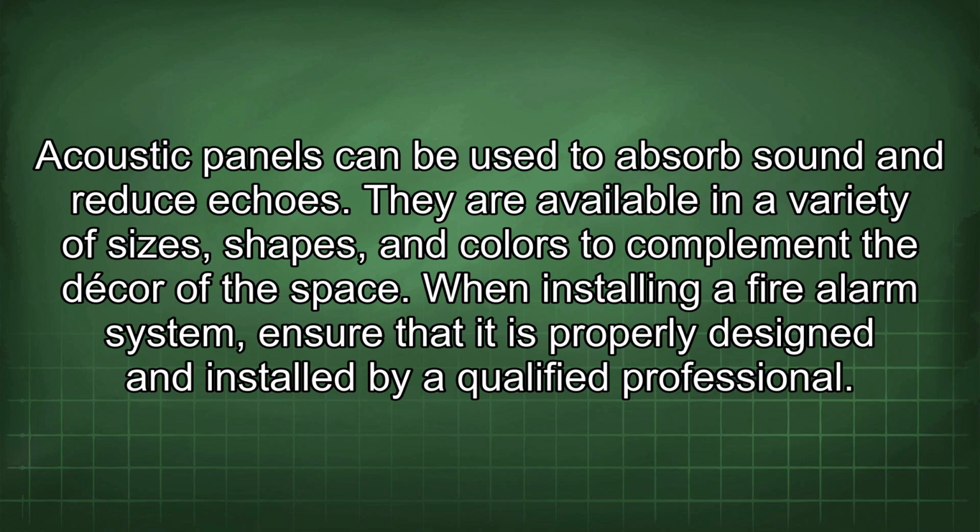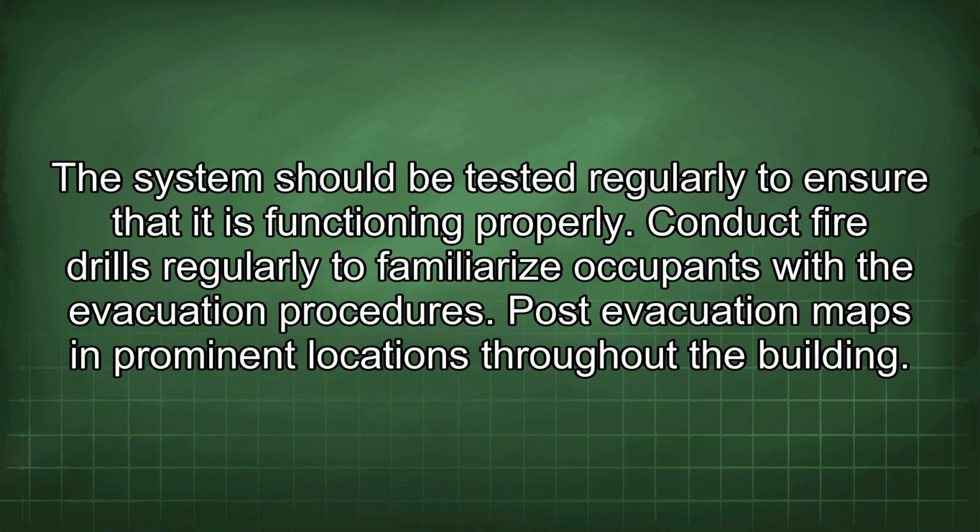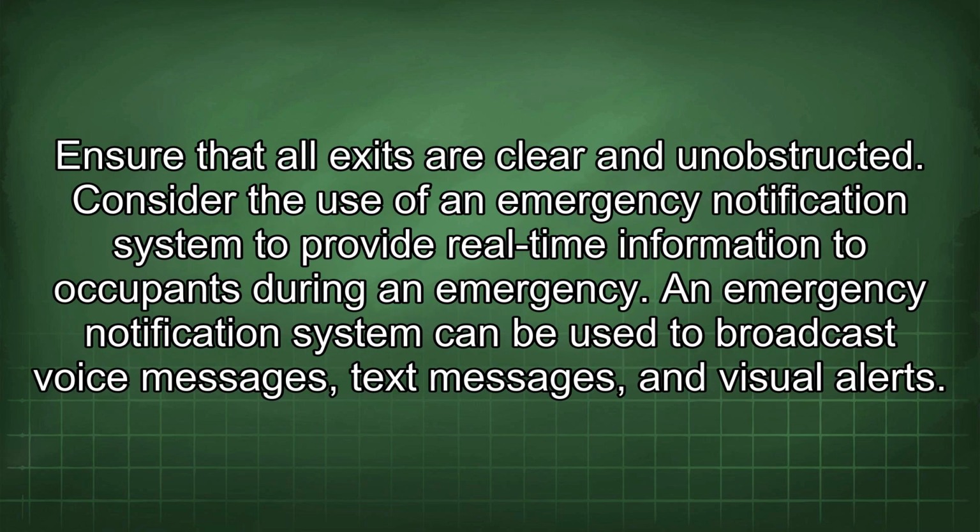When installing a fire alarm system, ensure that it is properly designed and installed by a qualified professional. The system should be tested regularly to ensure that it is functioning properly. Conduct fire drills regularly to familiarize occupants with the evacuation procedures. Post evacuation maps in prominent locations throughout the building. Ensure that all exits are clear and unobstructed.